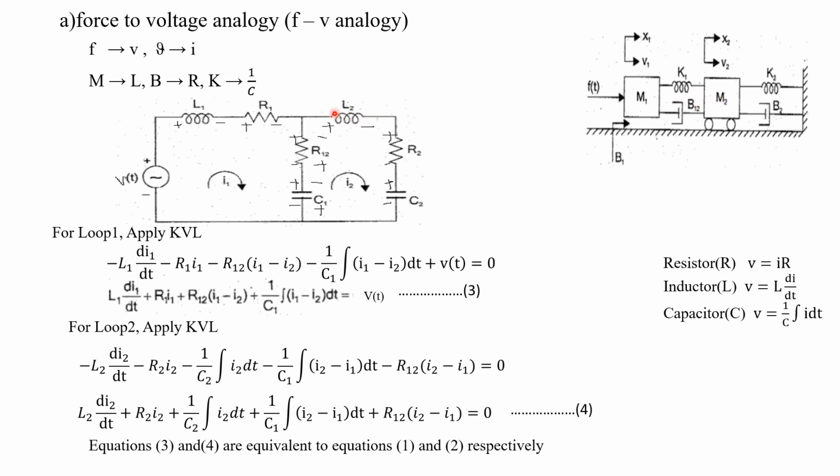What do we have to do? Here we have to represent the voltage source. While drawing the voltage source, on the right side you have to put plus and on the left side minus, because always in the loop we take the current direction as clockwise. The current should go out from the positive sign of this voltage source. So if you write the plus sign at the right side, then this rotation will match. Otherwise it will not match.